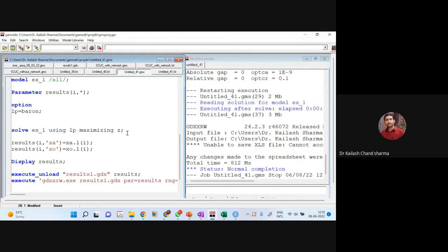Now, sometimes if you are working on an NLP problem, after the maximum iteration, your solver shows an infeasible result. It failed to converge. So you can also increase the gap between the solution and the iteration, since some gap is already there, so it shows infeasibility. You can allow that gap in the solver, and also increase the number of iterations. So those solver options are also available.